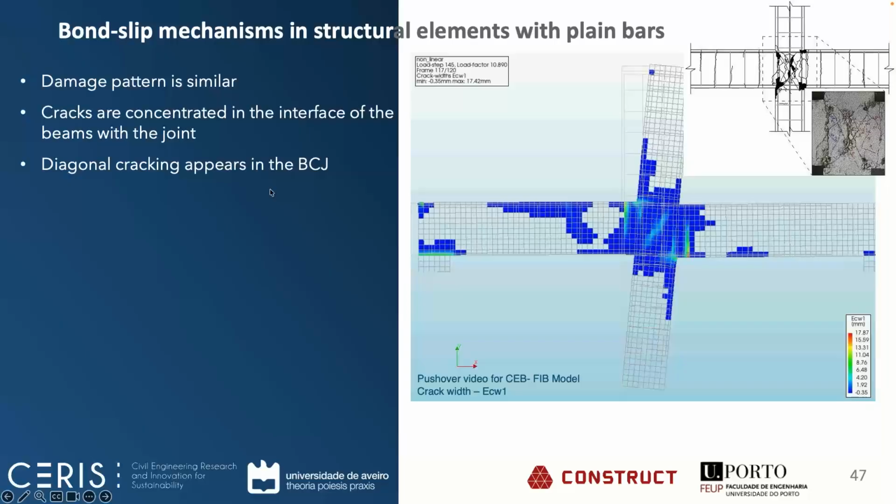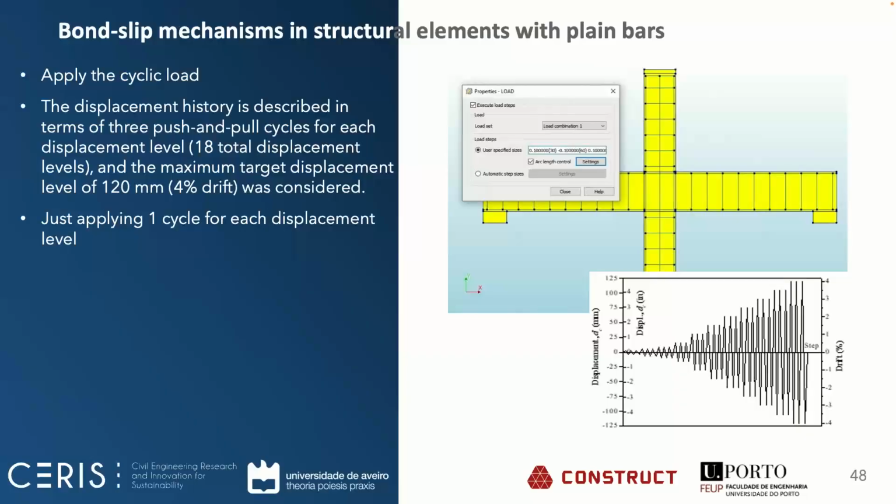So we are happy with the pushover, which is quite good because we can run a pushover in a few minutes, even with nonlinear analysis and this complex behavior. But we also tried to run the cyclic load. Of course, this analysis will take a few hours and it is harder to adjust parameters and so on. So that's why pushover analyses are always good to have as a first overview, and then we apply the cyclic load. Of course, we have applied it just for a part of the analysis to avoid hours of analysis and the space, and we apply only one cycle for each displacement level.